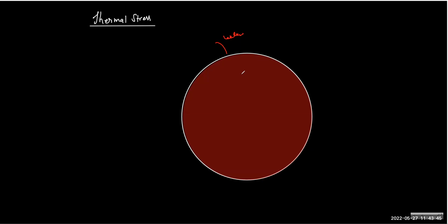So what you do is you first expand the iron ring in the red hot condition, which is roughly 800 degrees Celsius, or even let's say 600 degrees Celsius, and then due to expansion, you can fit the wheel inside, and then you cool down. It will become attached to the ring without any fault. Okay. Now that's very interesting.